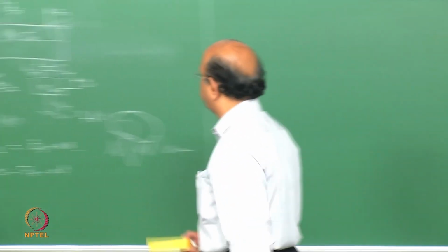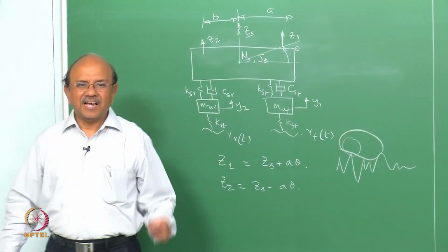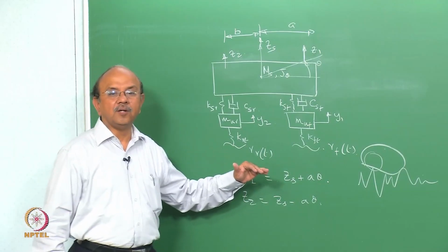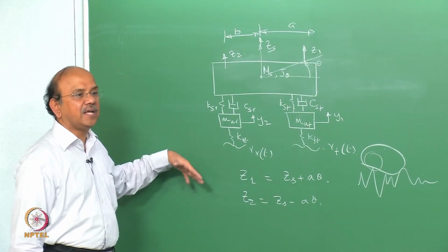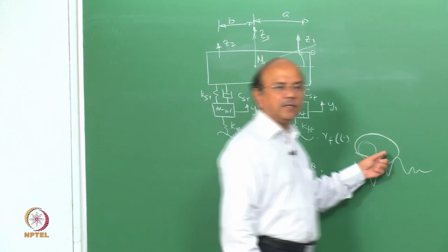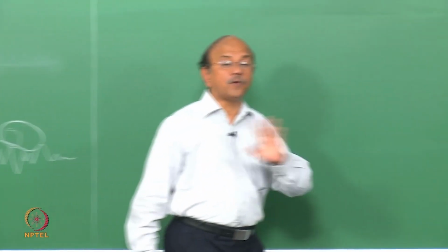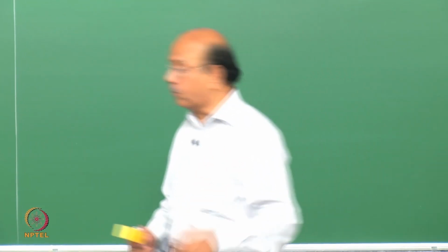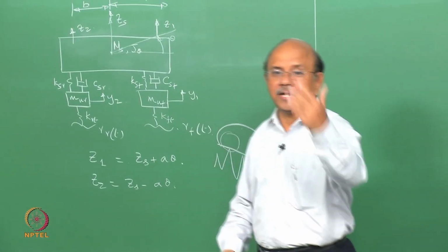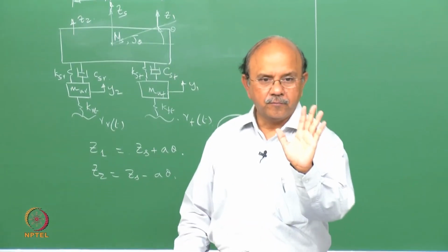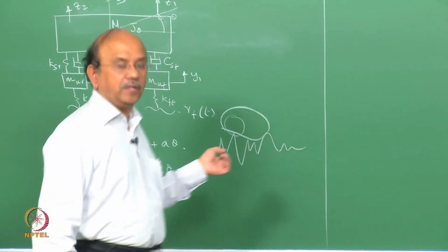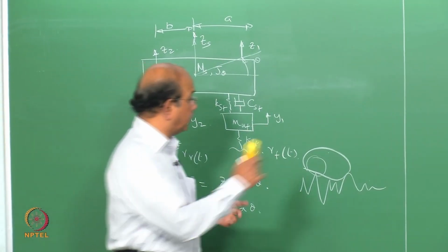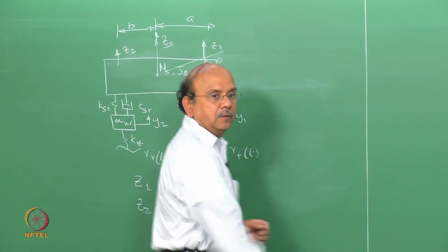So when I put this RF and RR, they are not road inputs, as is usually stated in many textbooks. It's not just the road profile, but the profile which the car sees after this high frequency filter called the tire, which filters not due to its stiffness characteristics. We're not talking about that. I have already put that here, but more due to the envelopment characteristics. What goes inside is what is felt. If you sit in this tire, in this region, what you feel is what we call RF and RR. Do we really know what that is?